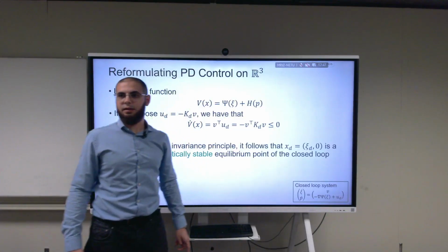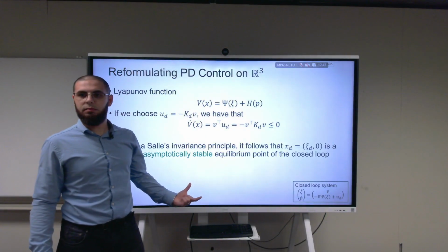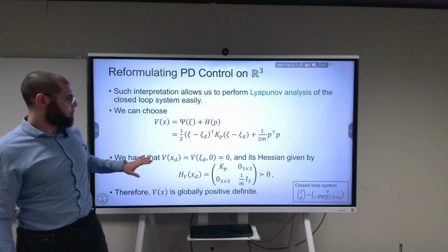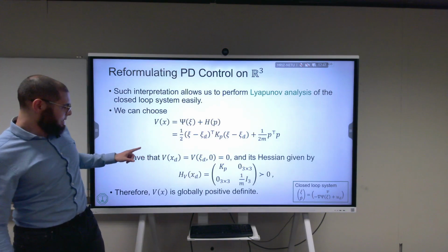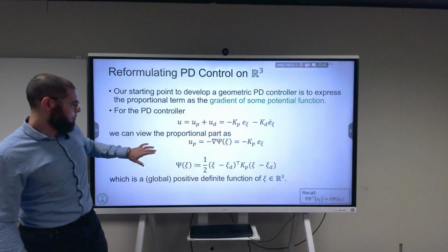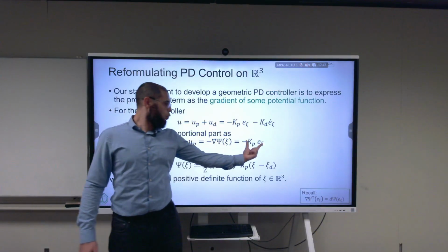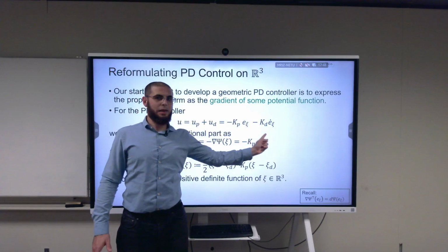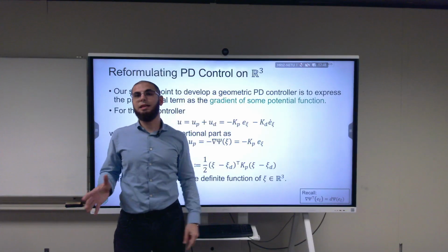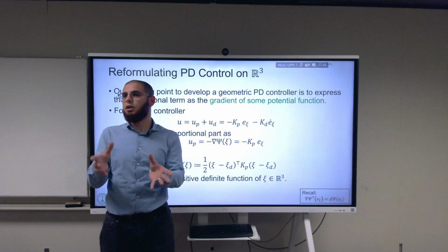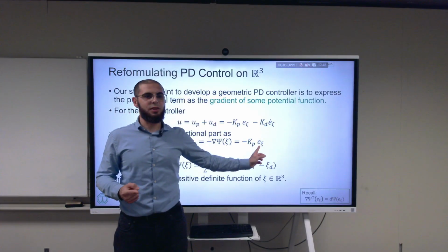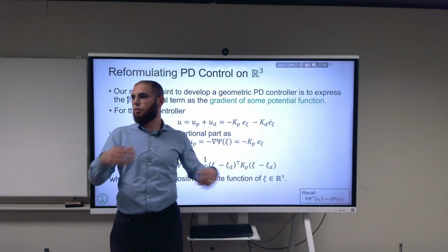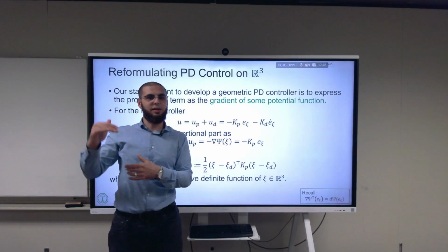Okay, so the gradient of that term, when is it equal to 0? At the equilibrium position. Exactly. So this gradient term, when is it equal to 0? When the error is equal to 0. So in the end, the largest invariant set has only one point when the error is equal to 0, or alternatively when psi is equal to psi desired, and the velocity is equal to 0. So all of these conditions, just write them one after the other.